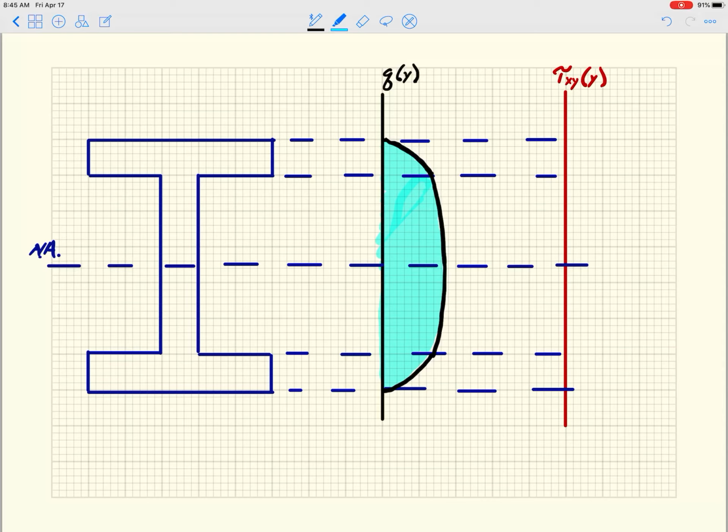So now for the shear stress, I'm going to take a cut here, and you can see this is my B sub F. So any shear flow in that area is going to get divided by this B sub F to turn it into tau xy, okay?